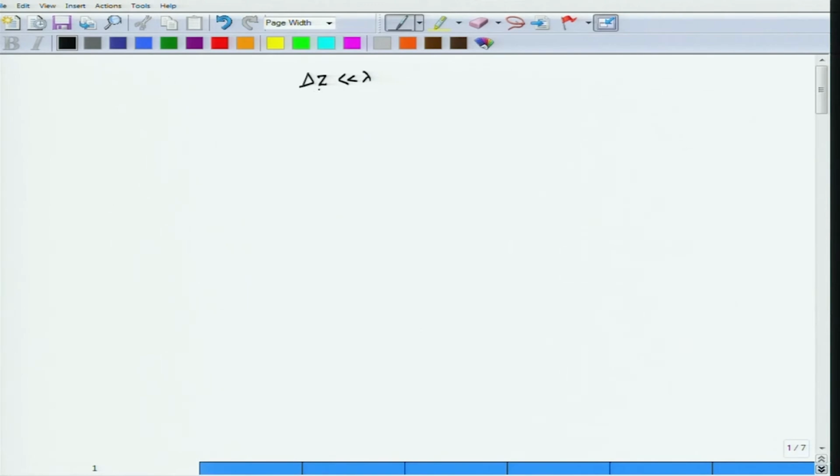Moreover, for this short length antenna, when we looked at its field pattern, we assumed a uniform current distribution which allowed us to simplify the expressions for magnetic vector potential, and from the vector potential we derived the expressions for electric and magnetic fields. So, we assumed a uniform current along the z direction, the antenna was oriented along the z direction, and then we obtained components for the electric field. We saw that the electric field components would be Er and E theta, whereas the magnetic field component would be H phi. We also saw three zones of regions, or three zones of operation around the antenna.